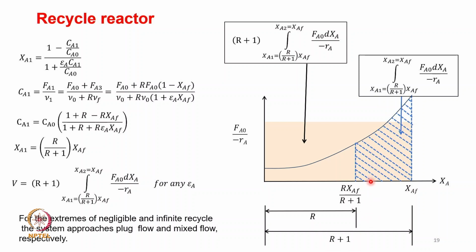This is that small integral again, and you need to multiply that R plus 1 times. So, if you have an intermediate height, you may assume this as a rectangle equivalent to one such rectangle, and you multiply that R plus 1 times. This is how geometrically we find out the volume, which is of course the key design parameter for any processing.